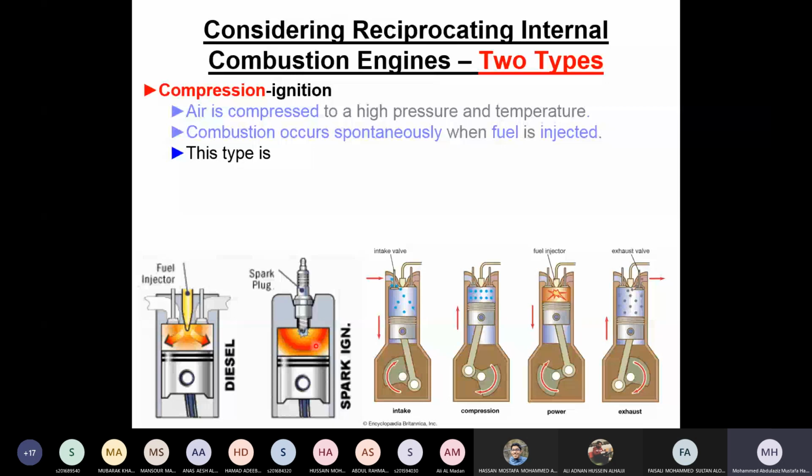So this is the difference between spark ignition and diesel engine or fuel injection. In a spark ignition engine, I have fuel and air, and the temperature is lower than the self-ignition temperature. Then I have the spark plug to increase this temperature. We have to make this controlled combustion, which means that we burn one layer here, and then the next layer, and the next. We don't burn it all together, otherwise this will be an explosion and the engine will be cracked.